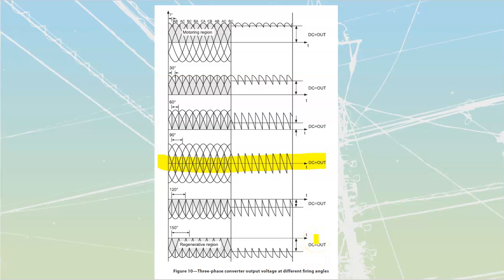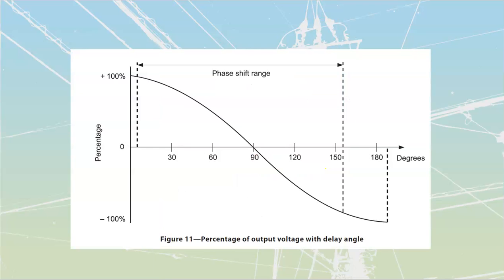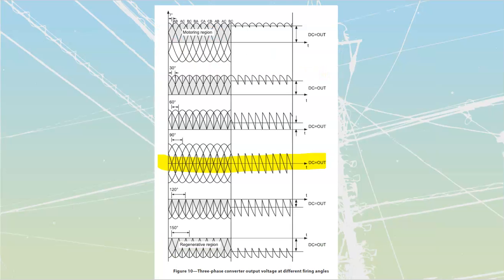Really what this will do now is I have reversed my value of DC that I'm going to have on the output. I'm going to have a certain amount of phase shift range that is going to be based upon the controller's physical components, the speed of operation, what we call the propagation delay of the electronics. All of that stuff combines together to create this. So that's going to be this to this over here. Somewhere in between those two ranges is what we are going to have. This phase shift that they're showing here is for this specific set of controls that we have over here.